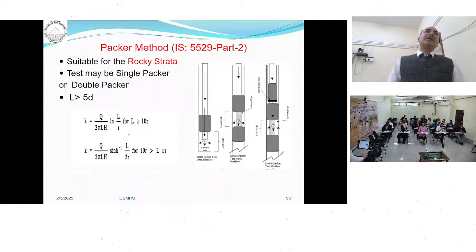If you are conducting a test in a rock and there is no fracture or cavity, then what is the probability? Probability is zero. Only in the case of rocks where fractures are present, the water will seep in. It is an indicator, because when you get the rock cores, it is not clear whether they had some cracks or not. By conducting this test, you know that the rock is cracked.